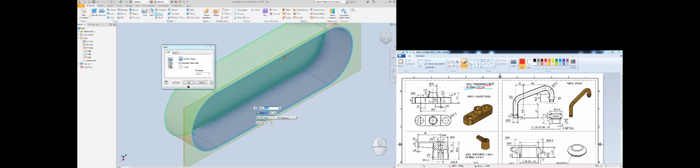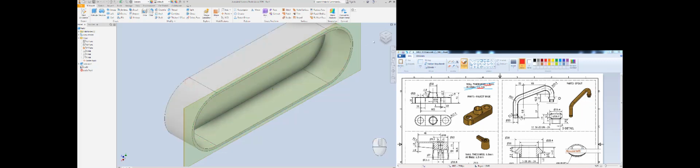And by this selection, the remove faces selection, which you have in the command, it is waiting for your selection. You can just select the face to make that feature an empty feature here. And from the thickness selection, you can just select 1.8 millimeter inside. Let's create this one first. The other side, we also have some holes here.